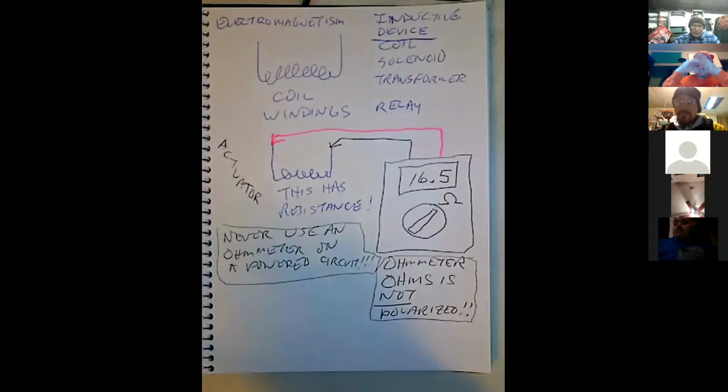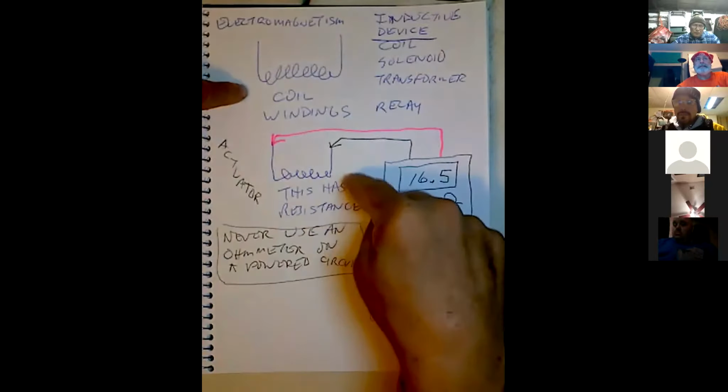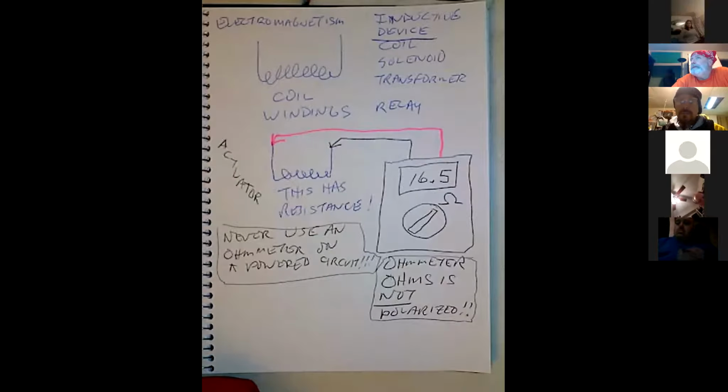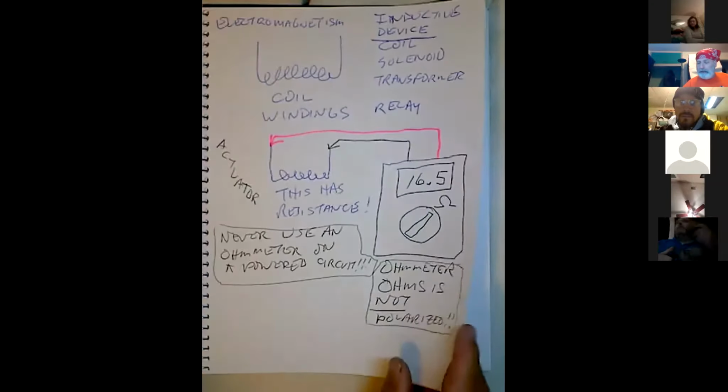Should plummet. It should go away. Now, if you send a signal to open this and the pressure doesn't go away, then it's not working. Does that make sense? Now, the reason could be electrical, the reason could be physical, but just because it works electrically doesn't necessarily mean that it works physically. The valve actually comes out, but it's a good indicator.